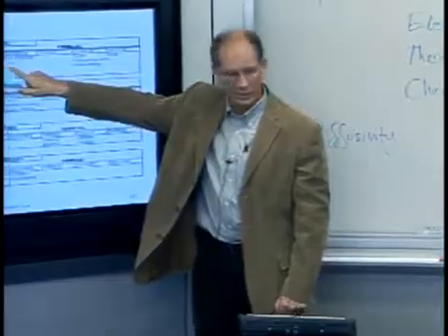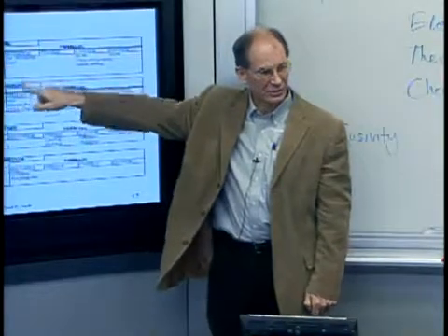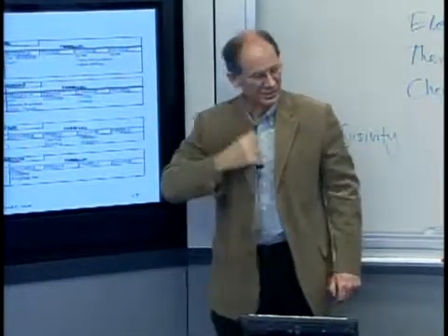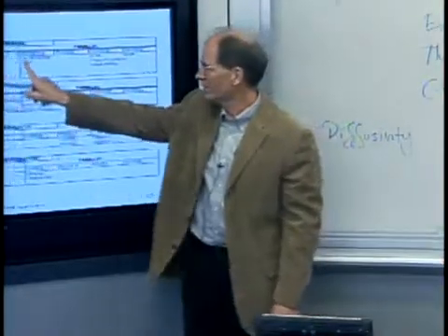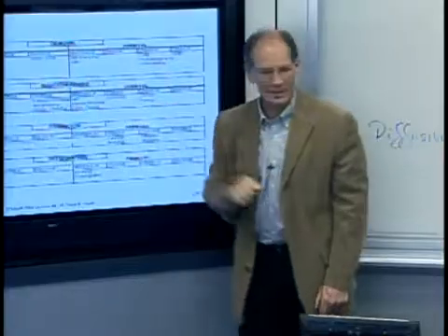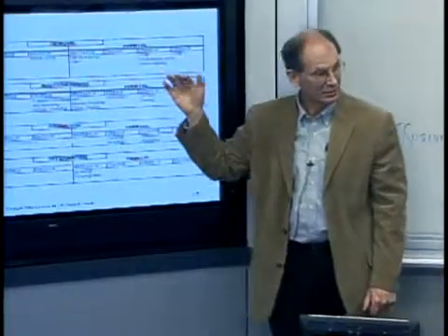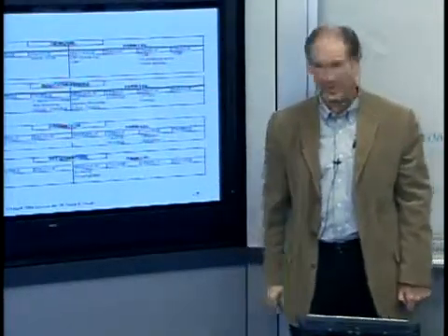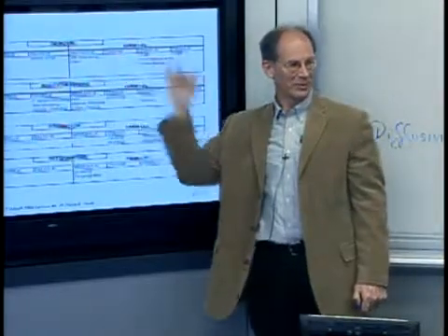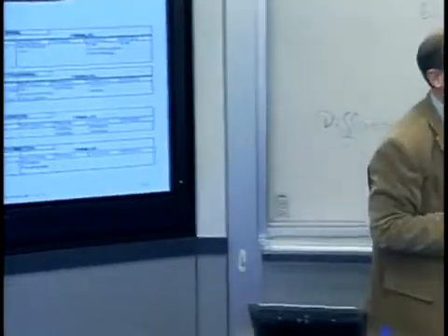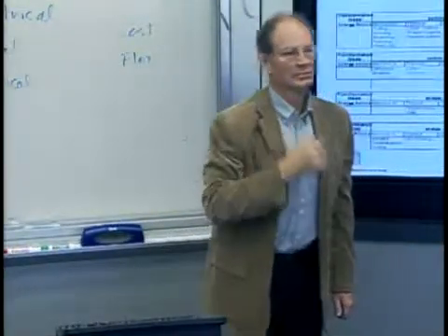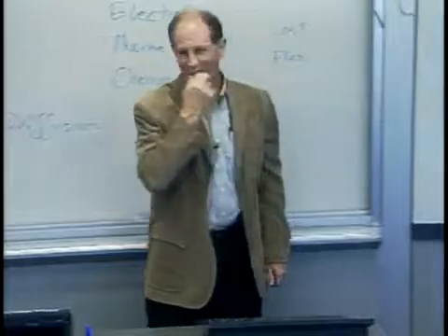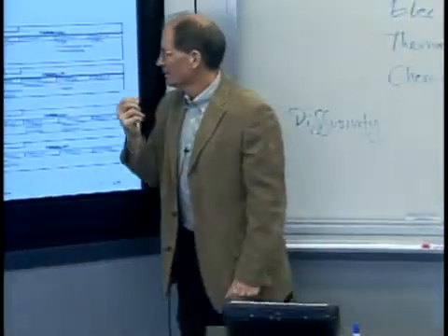I think Dwayne has already talked about chemical mechanical polishing, which I'm told by the experts in the field is really mechanical polishing, right? So if we take the C off of there, then CMP is a mechanical parallel process. If it's a chemical mechanical process, then I guess it has to show up in both of them. Which is it? Is it both? The chemistry softens the surface enough that the mechanical operation can occur. So you have both. But the chemical by itself would not remove any material.